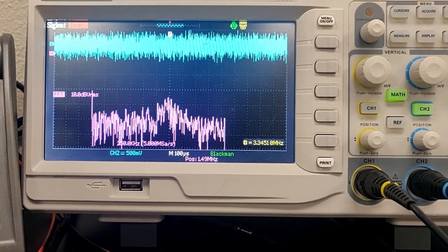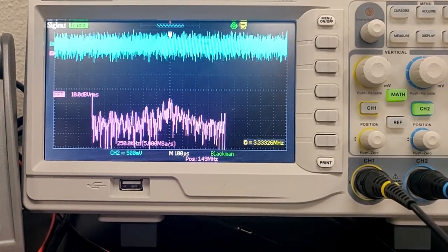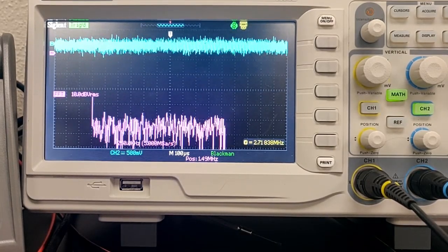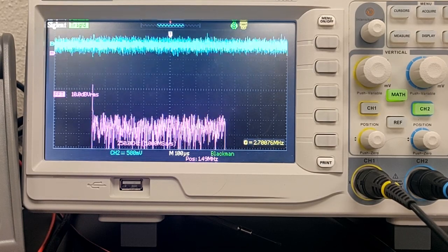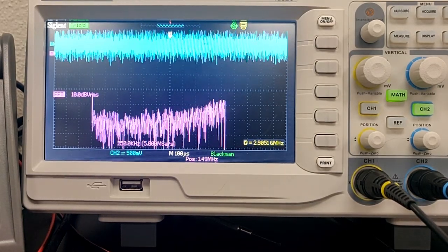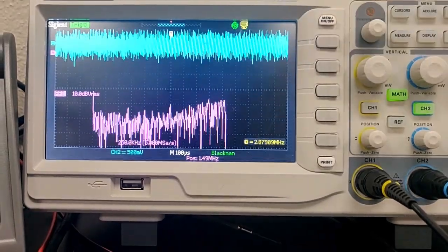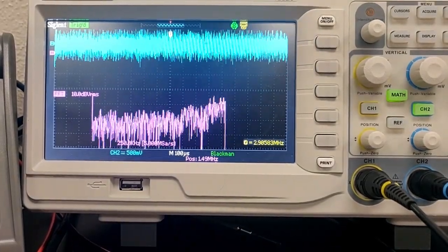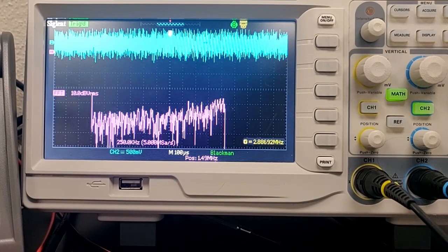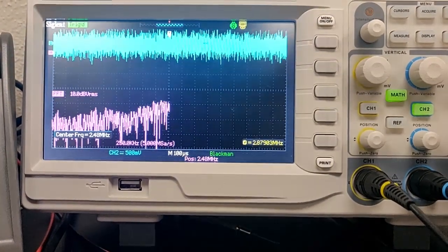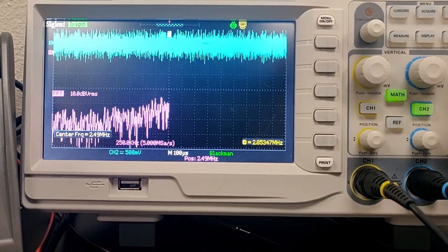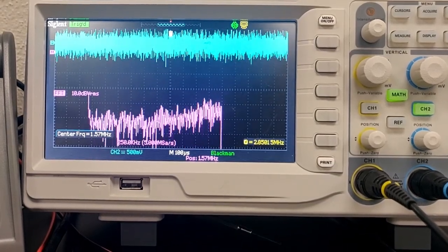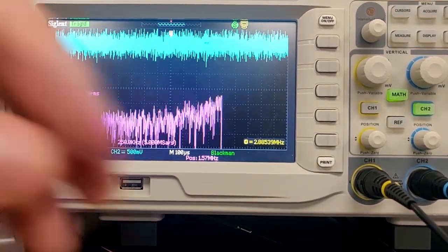So a much larger resonant frequency, which hopefully makes sense because we are decreasing our inductance, and that's inversely related to our resonant frequency. Okay, so now I'm going to switch the leads so that we are measuring the inductance from the center tap to the short end of the inductor, and we can see that it's past the range of our window. The peak is around here, but it's very spread out, and I don't think we're really going to pick up anything. If we go all the way to the end, we're seeing something around 2.49. That's not a very defined peak anyway, but it definitely still moves to the right, which again is consistent.